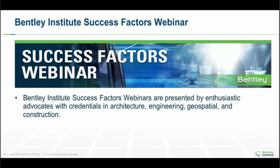And just maybe as a matter of interest, when you tell a program that this is a dog bone system, you have the option to tell the program to physically model the dog bone, breaking it up into short segments where the stiffness of the beam is being changed because of the dog bone.